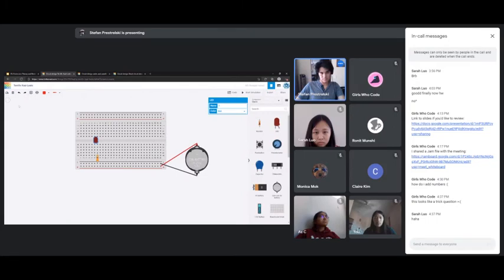And I think we'll give it a nice yellow color. Lastly, just have a wire connect that to ground, and then color that black. Start simulation, the light turns on. This is how we made a little basic circuit.